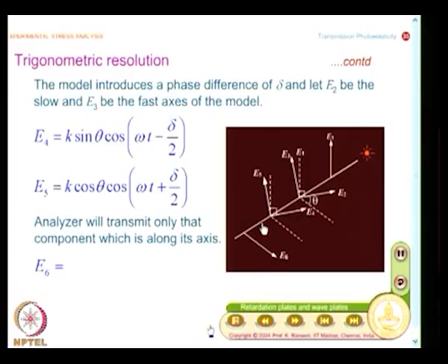Theoretically, when you are looking at a plane model, it is as thin as a plane, but physically we use a finite thickness. So, we bring in some engineering approximation, and we also say that the principal stress direction remains constant within that thickness, and we do this as two operations. First, the intensity amplitude, the amplitude of the light vector, changes. The second case, we put in the retardation appropriately, then it comes out.